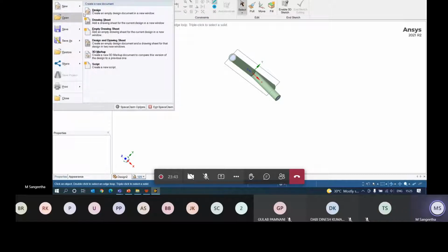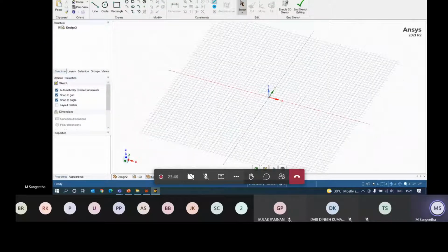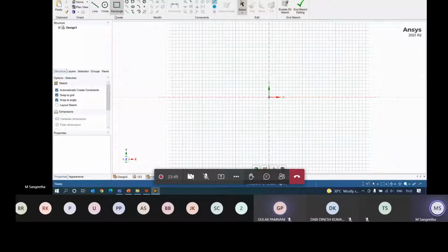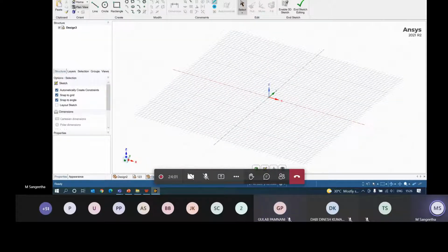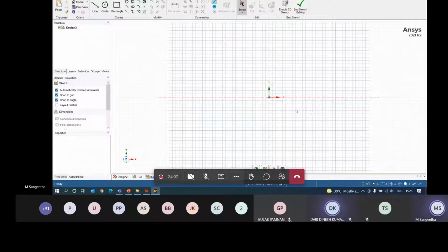Now let's take a fresh screen and we will understand how to work with designing, right? First, let's understand the Sketching tab more and try to start with it. You have the Home option here: wherever your geometry is lying on the screen, just click on Home and it will come to the center. Then you can set your plan view, either from here or from this quick toolbar, Plan View, to set your plane. Then you have different orientations available, left, right, or isometric, whatever view you want, you can have from here.